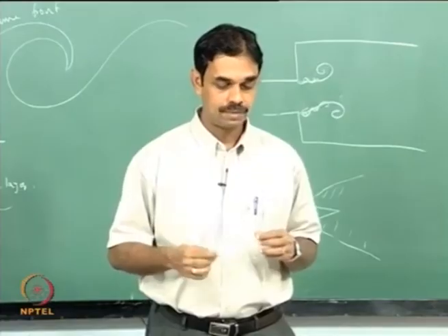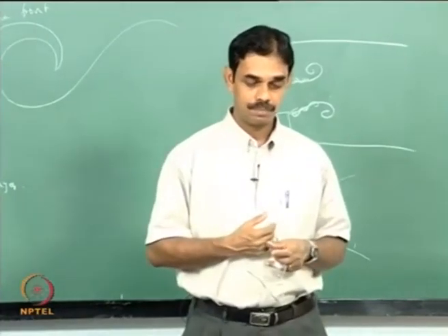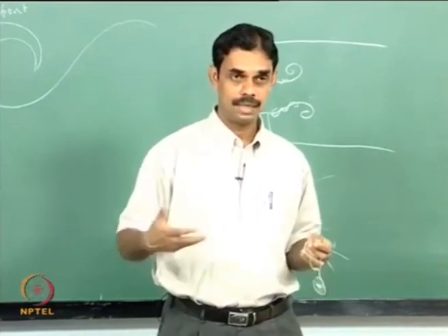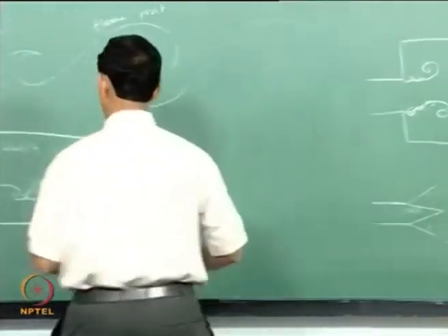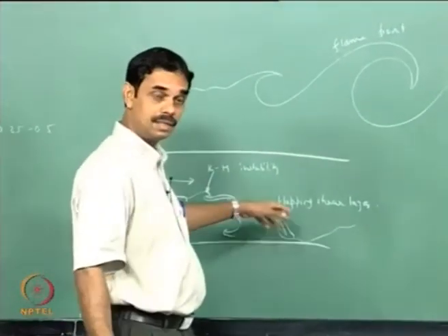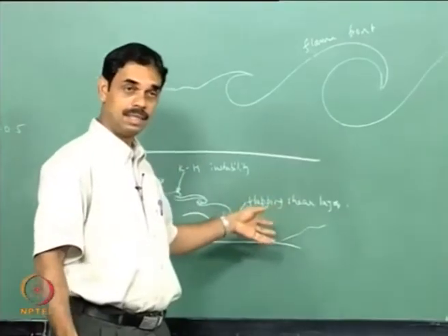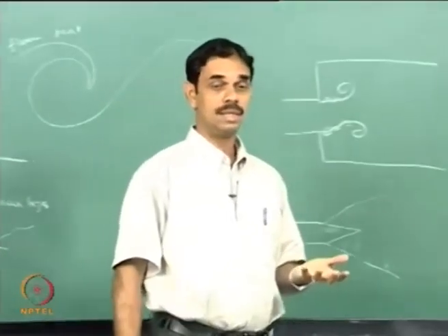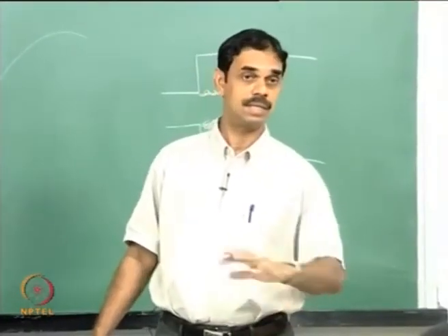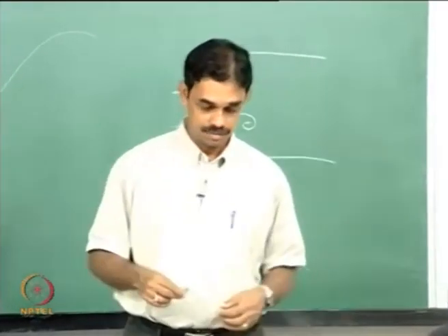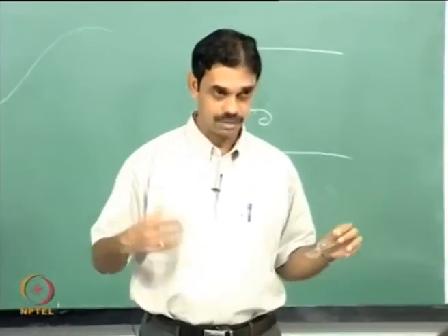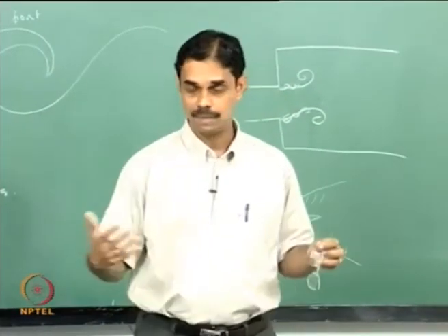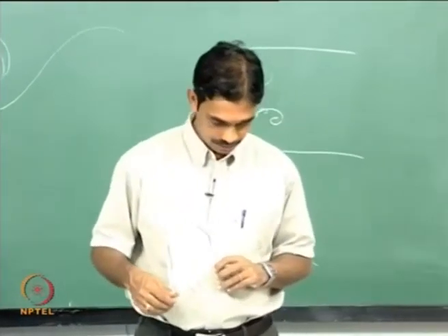The energy is supplied to the acoustic field if the heat release oscillations are in phase with pressure oscillations, and if it is out of phase it won't be adding energy. Sometimes some part of the flame may be adding heat in phase, some other part may be adding heat out of phase, but what matters is the net energy addition to the acoustic field. Some part may add, some part may take out, so the net energy addition is what decides whether you are going to have acoustic driving and instability or not, and whether this net driving is actually more than the losses or less than the losses.